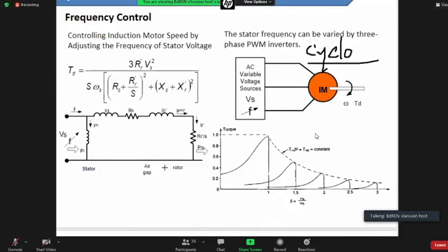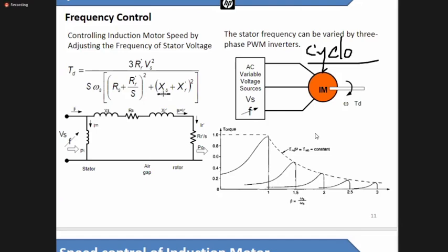You can see that if you decrease the frequency, it will decrease the value of XS and XR. All right, if you decrease the frequency, it will reduce the values of this XS and XR. That will result in increased current flow through the coils, which might not be tolerable. Okay, which might not be within the tolerable range. In that case, it will simply burn the coils. So it's better to go for higher frequency operation.